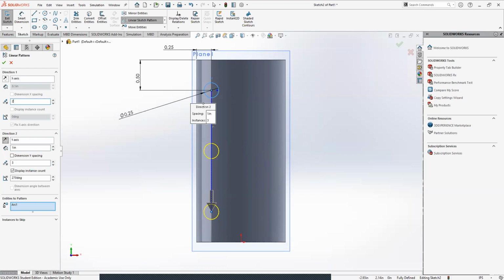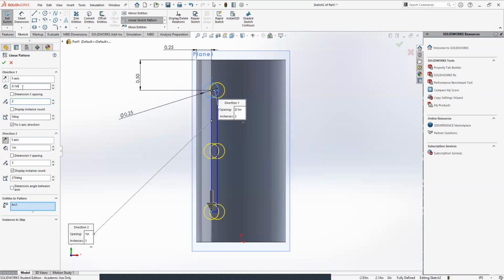One thing I could do now is if I hit 2 here, look at, say, spacing. Okay, I have my 6 circles, just like that, done, easy, right? Now that is a very easy way to do 6 circles. Look at that, 1, 2, 3, 1, 2, 3. Cool. And this would be done, kind of, right? Instead, I'm only going to linear pattern just 3 circles here, just because I want to show another feature on how we can get the other 3 to appear here. But this would probably be the easiest way to do it in this case.